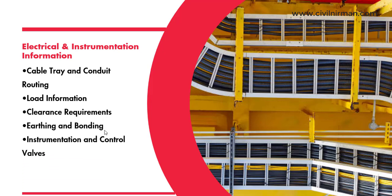See, in this particular, locations and specifications of any instrument control valves, junction boxes and related equipment to be mounted on the pipe rack, you need to identify and ask for the loading information if such information is missing. Then access and safety, so requirement for access to electrical and instrumentation equipment for maintenance and safety, including the walkways, platforms and ladders, right?